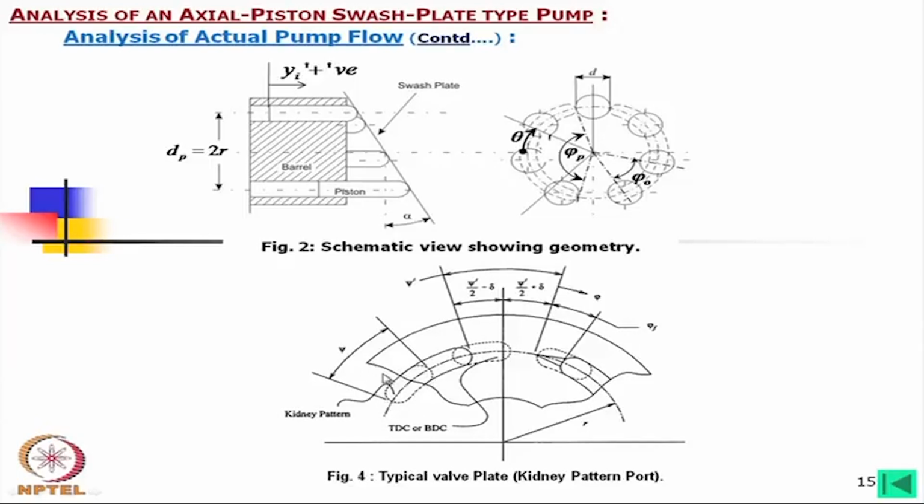Now, interestingly, say this included angle is psi. Ideally this angle should be equal. That means from this point to this point is the dead band zone, and it is almost equal. Ideally it should be equal, but you may find that on one side it is less and on the other side it is slightly more.